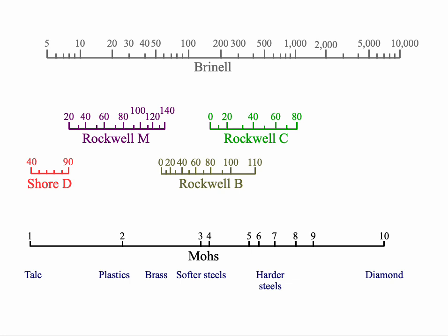Modern microhardness testers have built-in conversion software, but they're usually set up only for steels because that's what most people use them for. But if you are measuring the hardness of a different material, you've got to be careful about accepting the conversion that the software spits out.